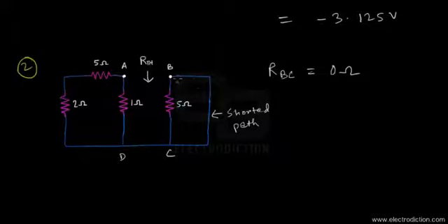So in order to deal with this one, we need to just eliminate this part of the circuit so that we'll only have the terminal B, since the net resistance would be 0. That happens when there is a shorted path in parallel to a resistor. So we're going to remove the 5 ohms resistor since it's of no use, and that would bring us to step number 3, as you'll find out shortly.